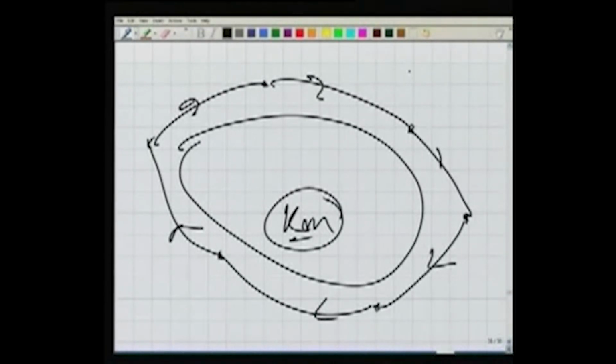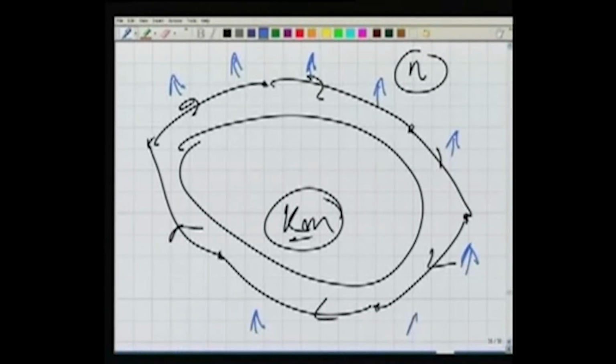And N stands for, when we are doing this exercise, I might have kept my instrument in several places. You know, how many settings of the instrument? All these are N. So we can use either the kilometer or the N, and we have to use the same throughout our entire project. So this is what N is, the number of settings of the level instrument, because we know, more is the kilometer,